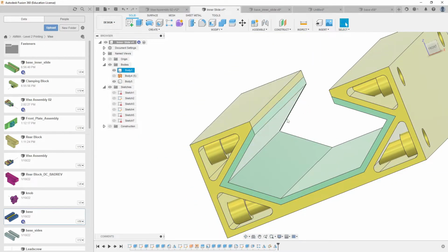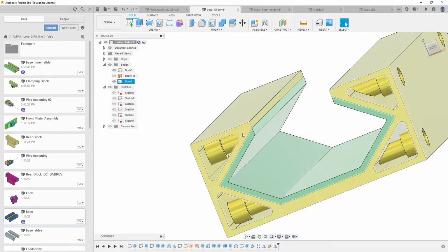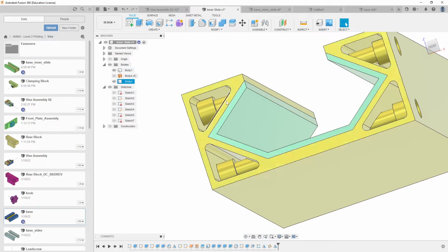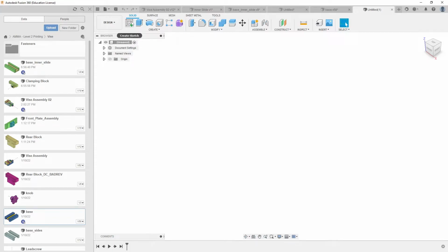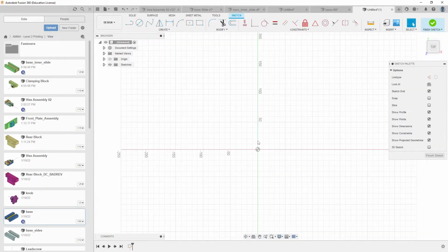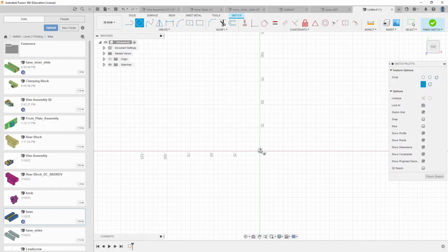So what we need to do is remove the tabs from this. Do we need to do it all over again and make a whole bunch of little holes in this? No, we don't. This is our next topic in this mayhem of a lab. This is Boolean operations. Boolean operations allow us to add, join, remove, or intersect one body from another. So this is another thing I should probably show you in a different window. Hugely valuable.